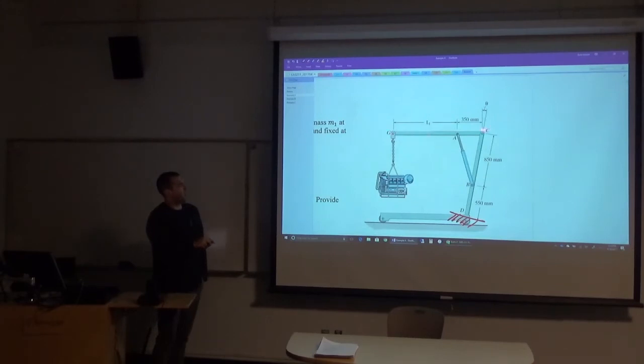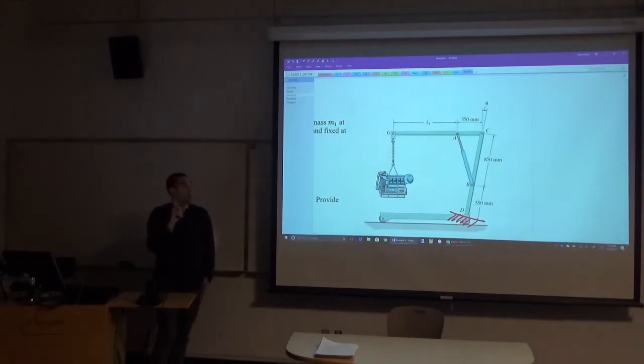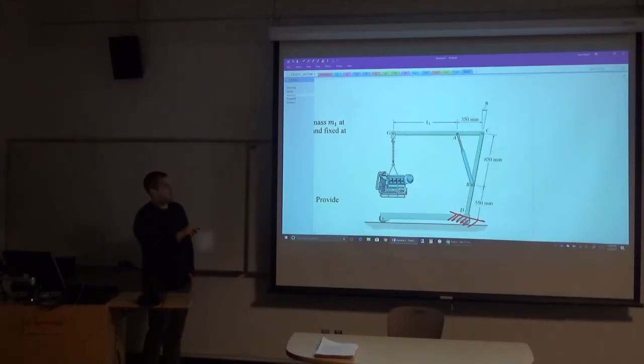So is this a 2-force member? Because I see what looks kind of like a pin over here, and I see a pin definitely over here at C. So I've got pins on either end, so it's a 2-force member, right? Just like a truss? What's the other criteria for a 2-force member? It has to be pin connected at the ends, and yeah, the only forces that can be applied have to be at the ends. Which means, what else, why isn't this a 2-force member?